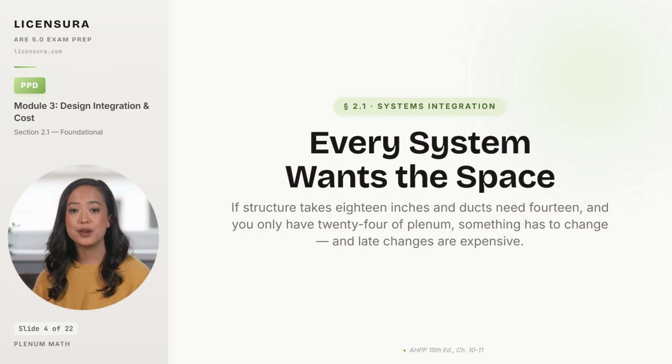Here is the integration problem that catches more architects than any other during design development. You promised the owner 10-foot finished ceilings. The structural engineer needs 18 inches of beam depth to span the open lobby. The mechanical engineer needs 14 inches of duct depth, plus 6 inches of clearance to route supply air through the same zone. That adds up to 38 inches of structure and mechanical, plus your ceiling assembly, plus your finished floor. And your floor-to-floor was set at 12 feet 0. The math does not work, and someone is about to lose either ceiling height, beam depth, duct size, or floor-to-floor.